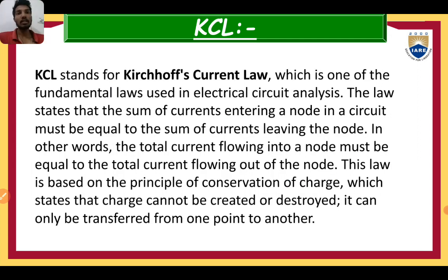KCL. KCL stands for Kirchhoff's current law, which is one of the fundamental laws used in electrical circuit analysis. The law states that the sum of currents entering a node in a circuit must be equal to the sum of currents leaving the node. In other words, the total current flowing into a node must be equal to the total current flowing out of the node. This law is based on the principle of conservation of charge, which states that charge can neither be created nor destroyed. It can be transmitted from one point to another.